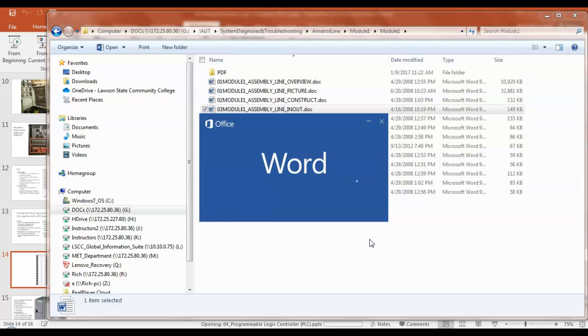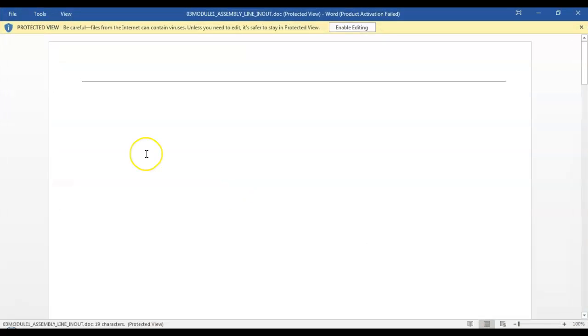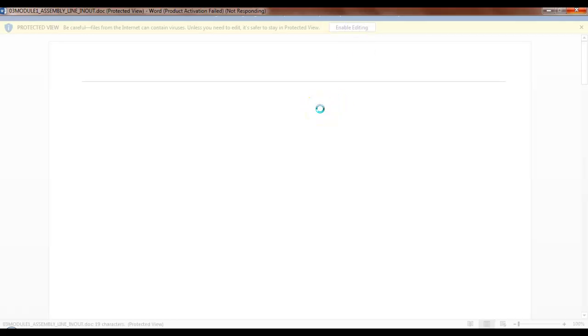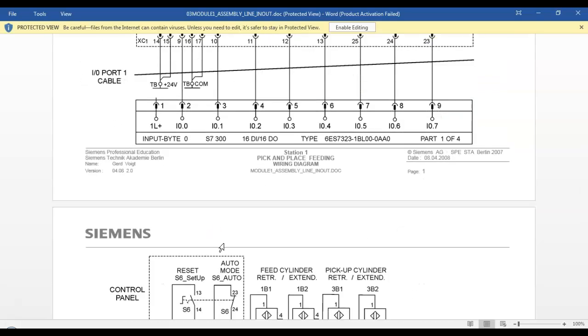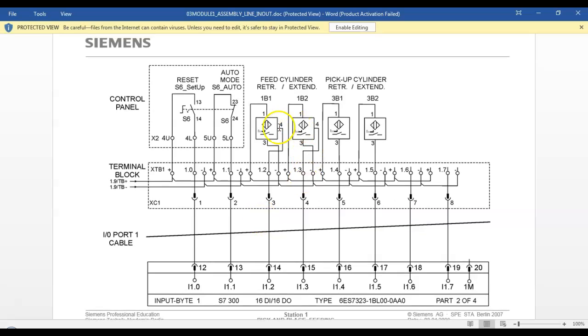Because I think the odds are power and the evens are your signal. So the odds are power and the evens are your signal. Well, is this a sinking sensor or is it a sourcing sensor? It's a solid state sensor. It's got to have both powers hooked up to it.